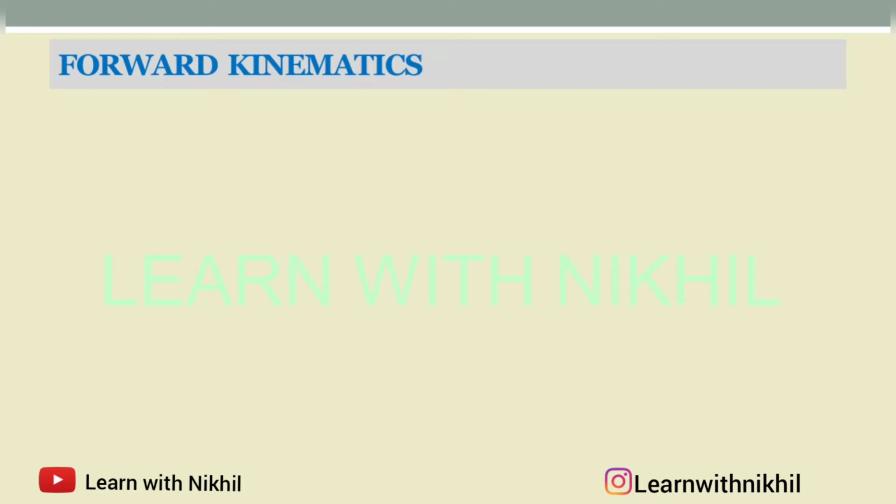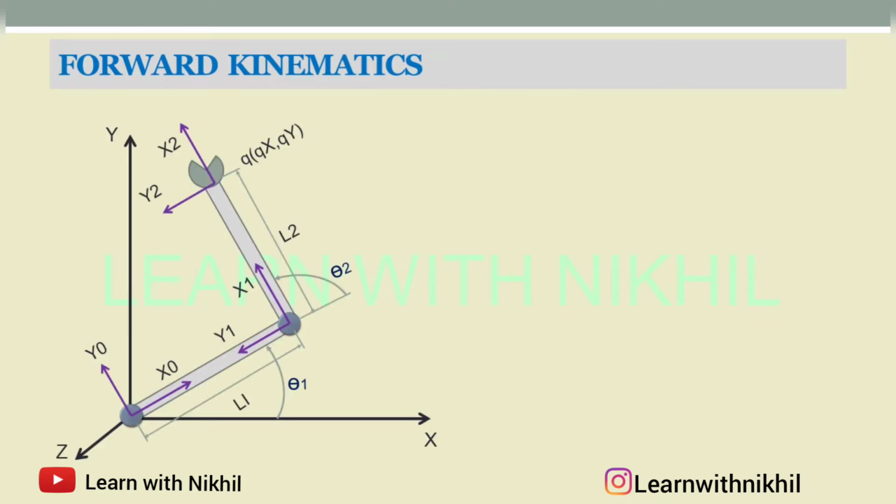Now to find the forward kinematics of this particular robot, you have to find out the position of this end effector with respect to its base. So to find the position of this with respect to the base, you have to first find out the position of this with respect to this joint and then this with respect to this joint.